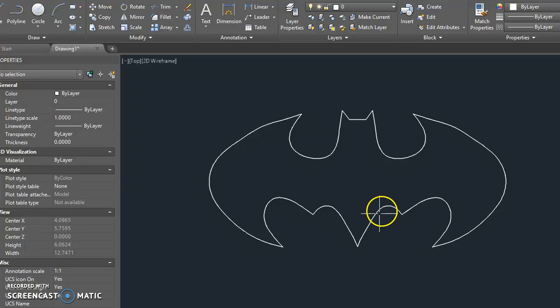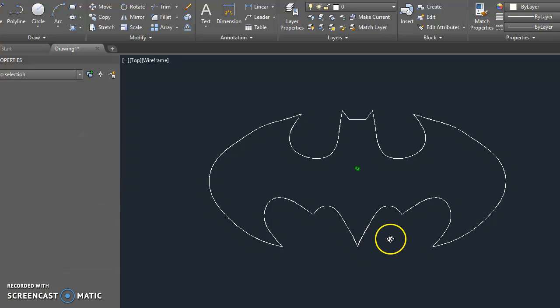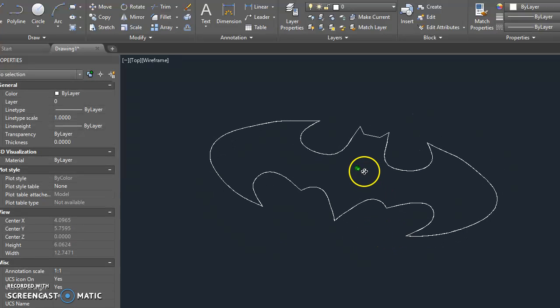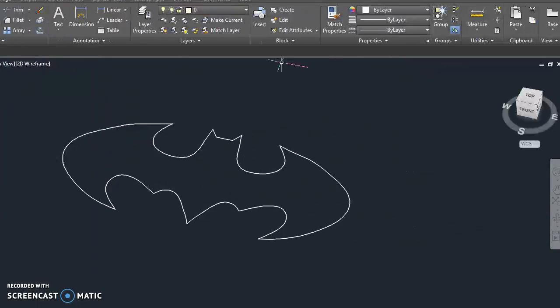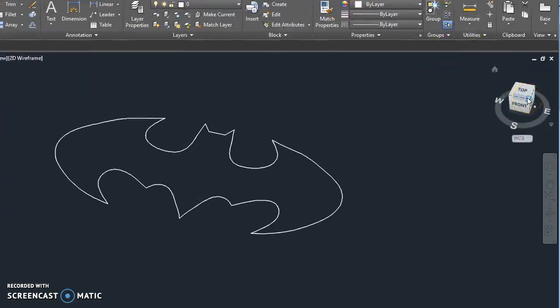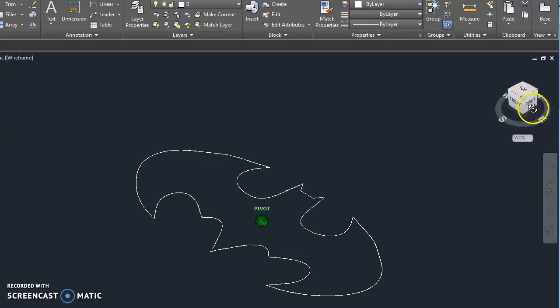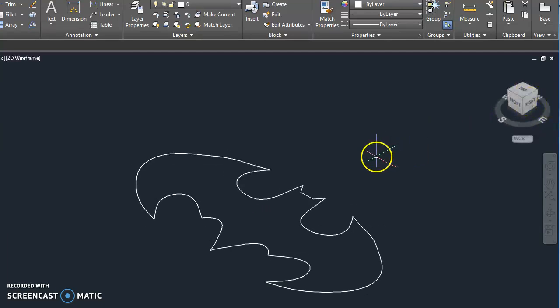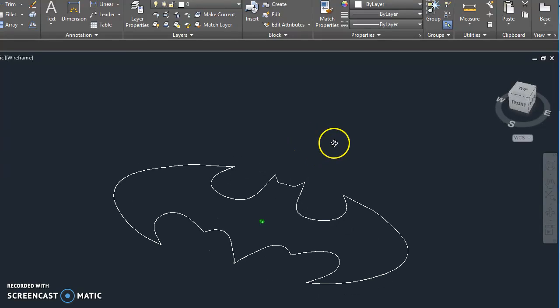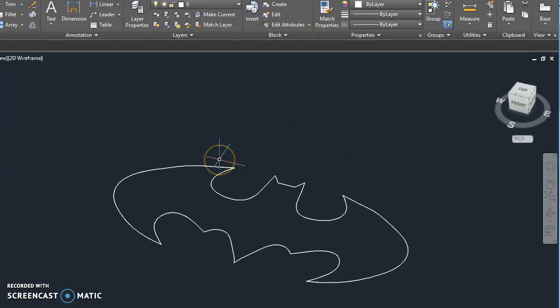Okay? Here's the last step on making this one 3D. Press Shift, press Scroll, and then you zoom up like this. Also, if you feel a bit more comfortable, you can grab the world coordinate system, and you can grab this thing too just by left clicking. You can move it around there, and pivot around. I'm a Shift Scroll type of dude, so there you go. All right, so I want to make this, let's say, a 1/4 inch thick. I don't know how much I'm going to make your guys's. Have not decided yet, but let's go 1/4 inch for right now.